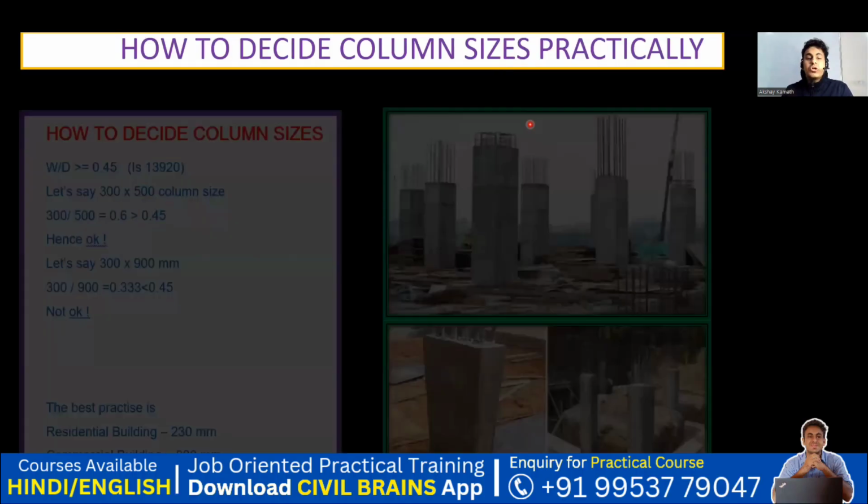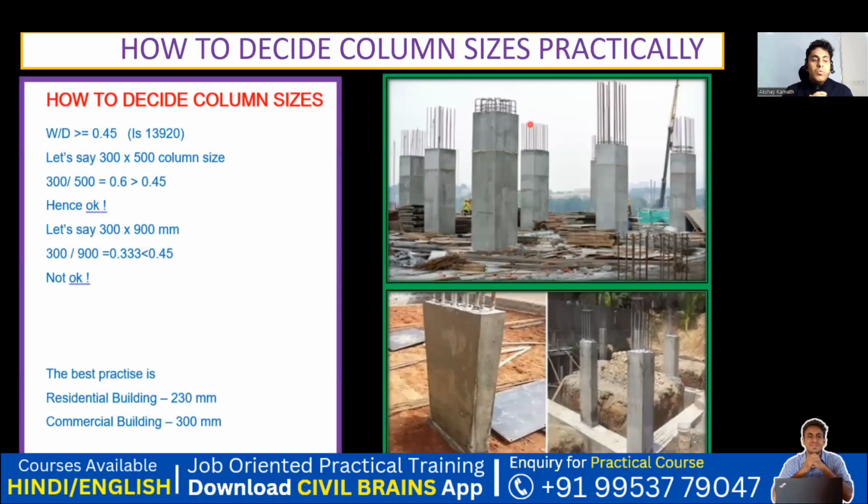So we'll see how the column sizes are to be decided. Now, to decide any column size, we need to follow one rule, that is the width by depth ratio should be either greater than or equal to 0.5. That is according to IS 13920. Along with that, I'll be telling you certain standard dimensions, but you can follow this. So what exactly is this width by depth ratio?